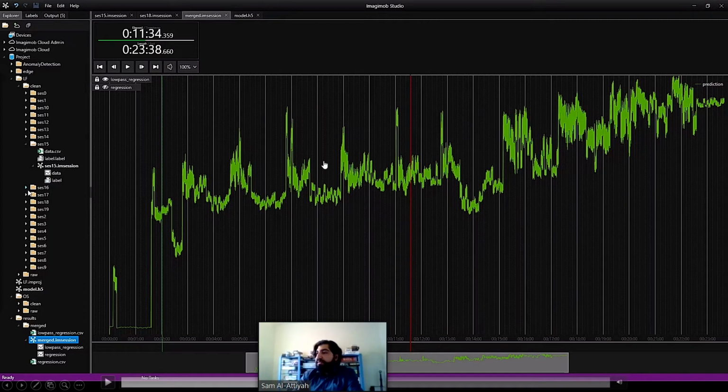So here we can see that there are 12 peaks, and that correlates to the 12 days that the machine was run, or the 12 cycles of the aging process. So one thing that could be done at the next stage is to actually allow the machine to stabilize before sampling the data so that you get a smoother curve.